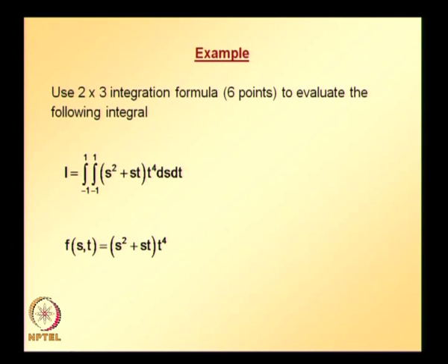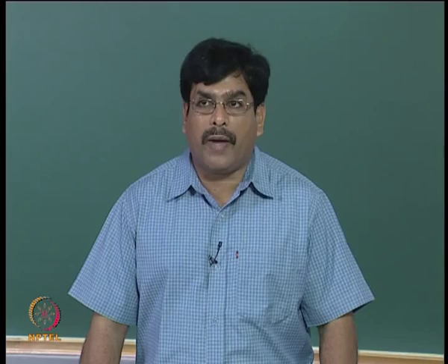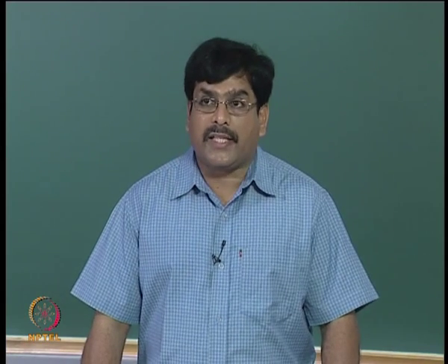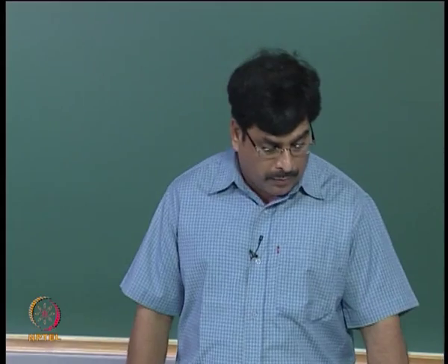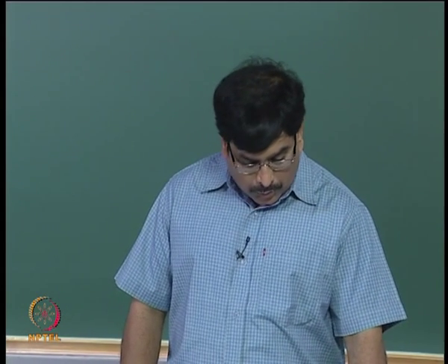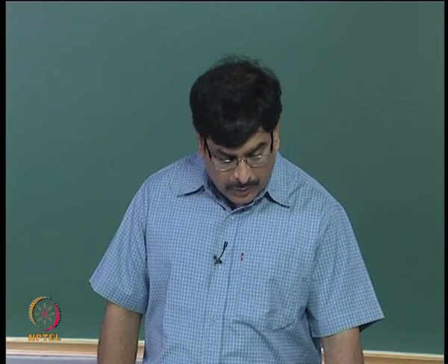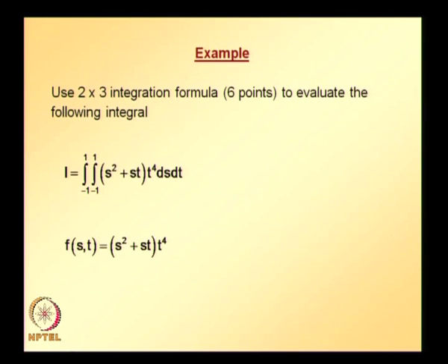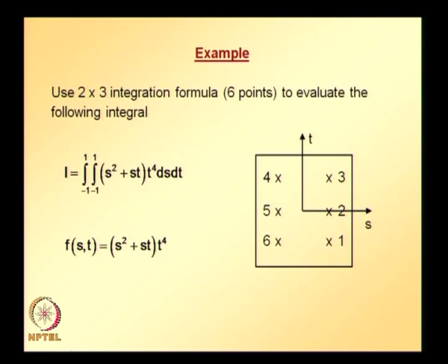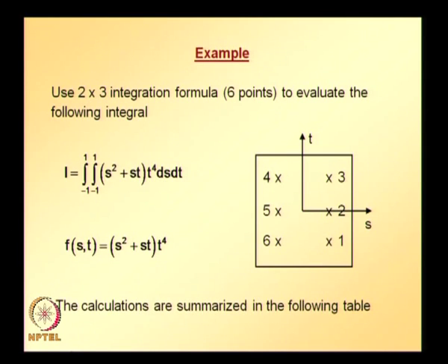So, the approximate solution that we are going to get by adopting Gaussian integration is going to match with the exact results for this particular problem when we adopt this integration. So, all the calculations: these are the locations of integration points. The details of calculations at each of these integration points and their locations and weights are given in the table.